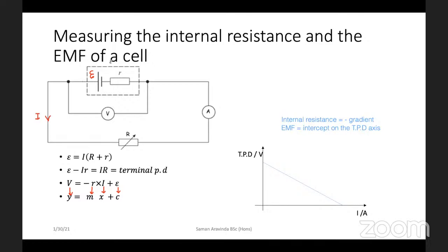Now, usually when we do this experiment, the same set of data is used for another experiment, that is what we have to learn at the end: the maximum power, internal resistance, and load resistance relationship. When we do this experiment, we know the potential difference and current through the circuit, so we take the power output of the variable external resistance and draw it against the external resistance.